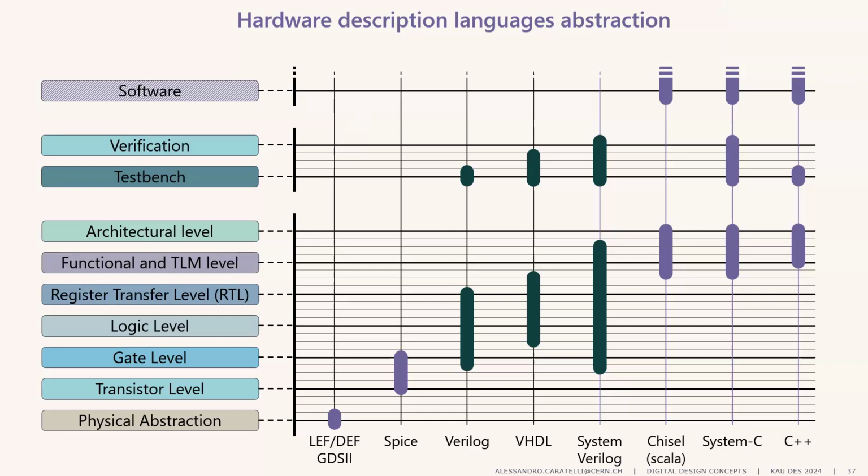While for open source hardware in terms of IP blocks, like blocks in Verilog or in higher level abstraction, in the last years there was a revolution. Now there starts to be a lot of open source, starting from RISC-V, with a lot of open source implementations of RISC-V processors that you can use, modify, and put inside your own design, and a lot of other IP blocks. Think of the Open Hardware Repository, or for RISC-V, the very nice cores coming from the PULP platform from ETH Zurich, which have become a sort of standard, like RISC-V became a sort of Linux in the hardware world. So in the last years, there's really been a revolution in terms of open source.